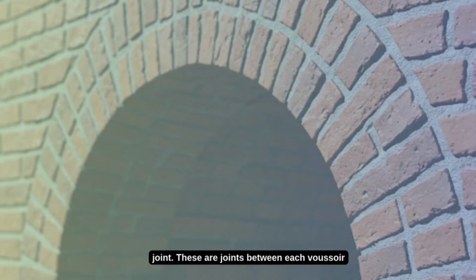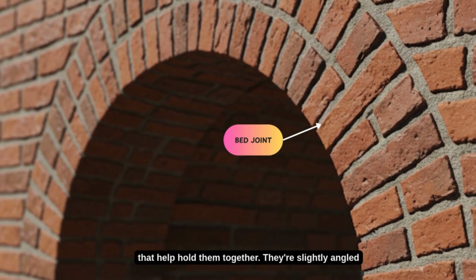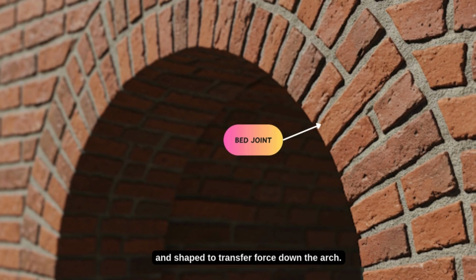21. Bed joint. These are the joints between each voussoir that help hold them together. They're slightly angled and shaped to transfer force down the arch. Every brick has its place, and every joint ensures it stays there, safely.